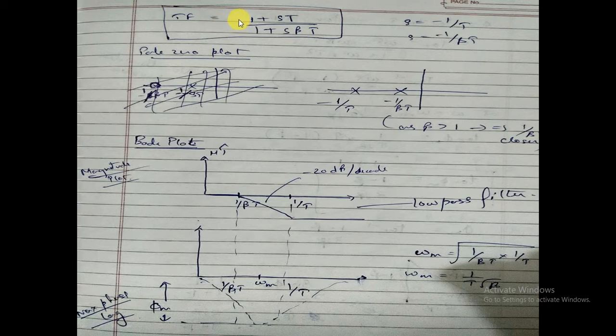It is the same as phase lead, but there was some alpha term out there which is not present in this, so that's the benefit of the lag compensator. So we get the poles and zeros, and as I said, beta is greater than 1, so the pole will be smaller in magnitude, but in the negative it will be closer to the j omega axis.